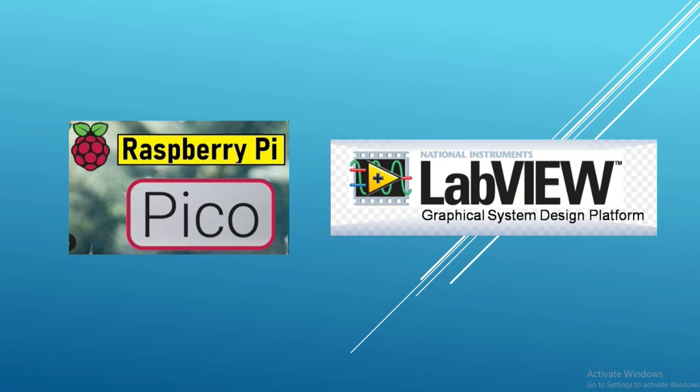pins. In addition, it has 2 UARTs, 2 I2C controllers, 2 SPI controllers, and 8 programmable I/O state machines. Also, the Pico has a built-in programmable LED, a 3.3 volt 12-bit analog-to-digital converter, 3 hardware pulse width modulation channels, a built-in real-time clock, and a built-in temperature sensor, which we'll be using in this project.